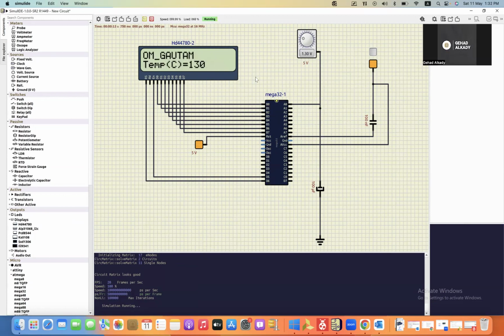If you calibrate your sensor, you will see what factor you divide the voltage value coming from the temperature sensor by to have reasonable values for the temperature.